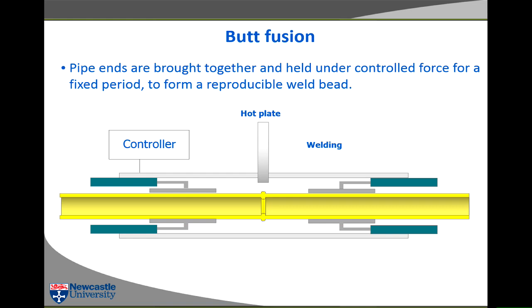And the main reason why the joint in a butt welded pipe is stronger is because you've produced this bead on the pipe, so you've effectively thickened up the section. But I say, don't run away with the idea of thinking that the bead is very large. It's not as large as I've drawn it there.